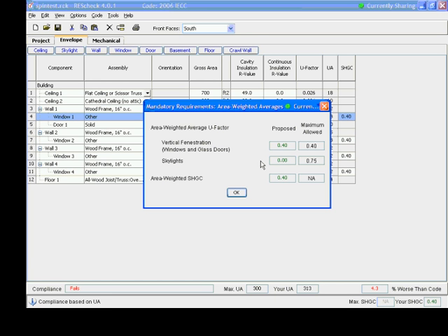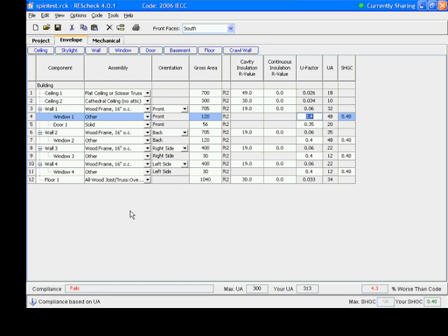What this means here is that I'm not meeting that maximum 0.35. I'm not beefing up anything else in this building envelope, so I'm not trading anything off. I'm meeting minimums here. You have to start trading off components in your building envelope before you can start trading off another component, and it would be this component, the glazing. So since there is nothing that's being increased anywhere, this is why this project's not meeting it.